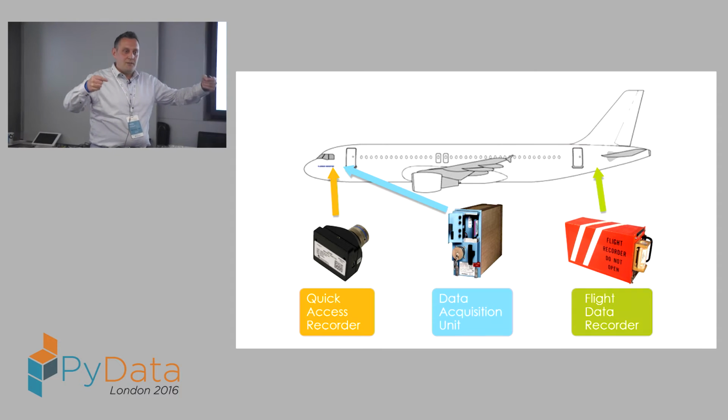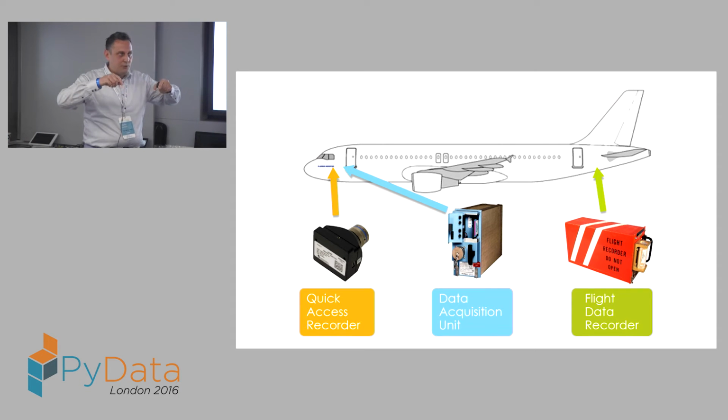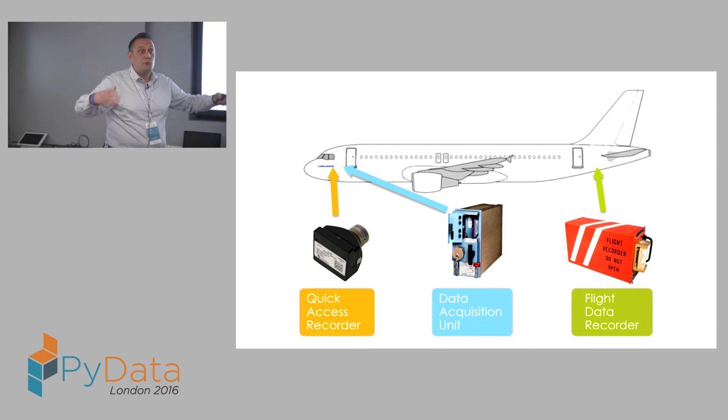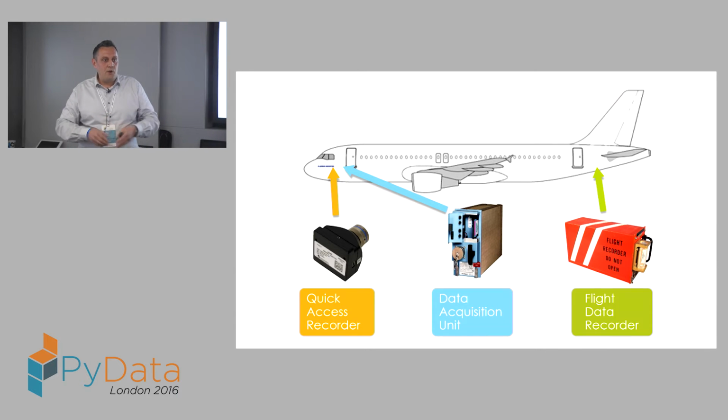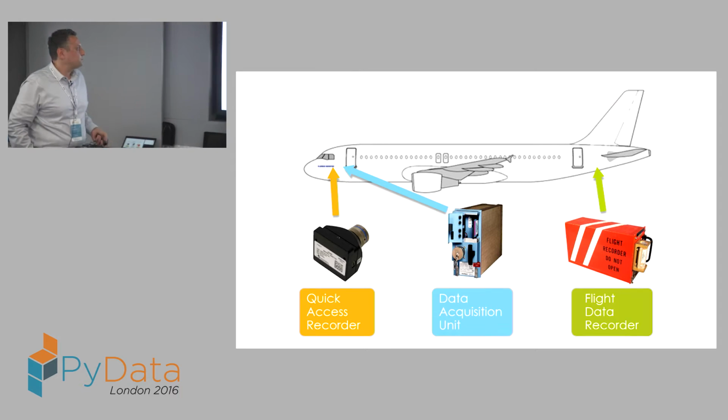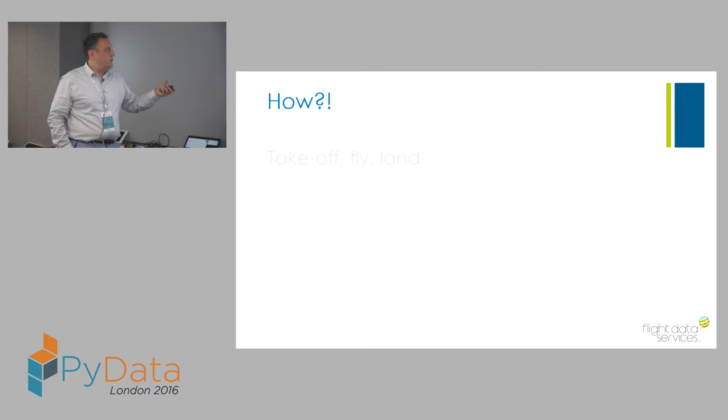First, you can't feed the flight data recorder with all the wires, 5,000 parameters, or 2,000 parameters, sorry. So first you have to condense these 2,000 parameters and then just use one wire to put it into the flight data recorder, okay?